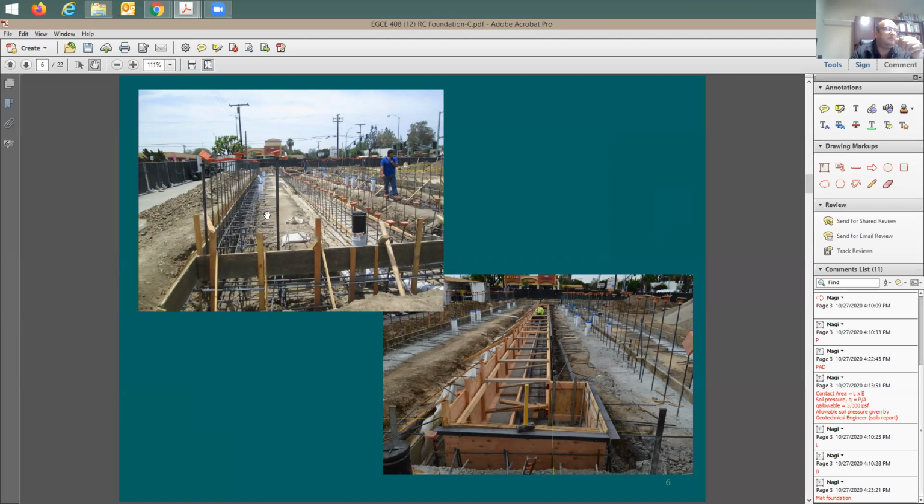First we pour the footing, right? And after we put it, we start to put the block wall, because this is actually a concrete masonry wall. It's going to be above it. So here's the footing, no rebars yet. Now you put the rebars, and then you put the dowels. They're going to be sticking up. And then once you put the blocks, after this, you're going to be doing the splicing of the rebars. You continue the rebars like this. So another rebar is going to come right next to this. It's going to go all the way to the top of the wall. So you call this a splice. The splice means the length, or the fact that you're putting 2 rebars next to each other.